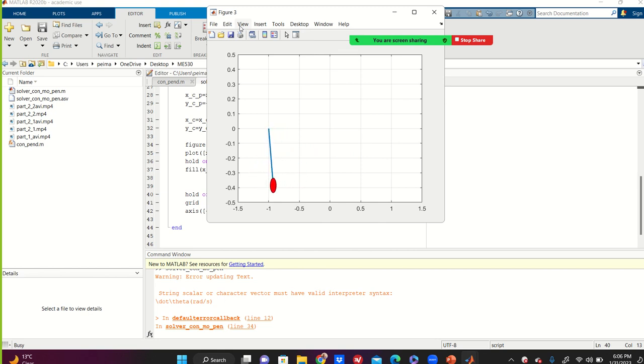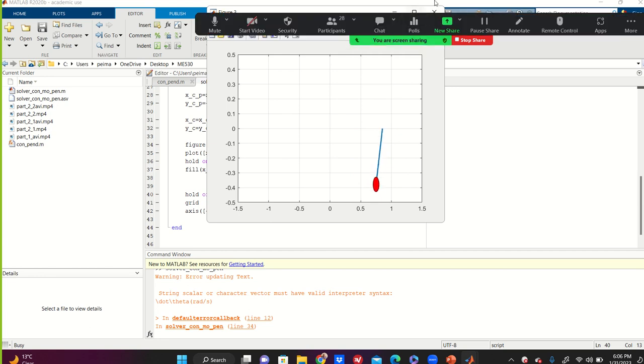But you as control engineer is to fix this. You have a disturbance that is base motion, and we want to keep the angle always 45 degrees here, not marginally stable. So you have to design a controller, apply a torque at the joint that makes that happen. This is your function as control engineer in this class. See what I'm saying?